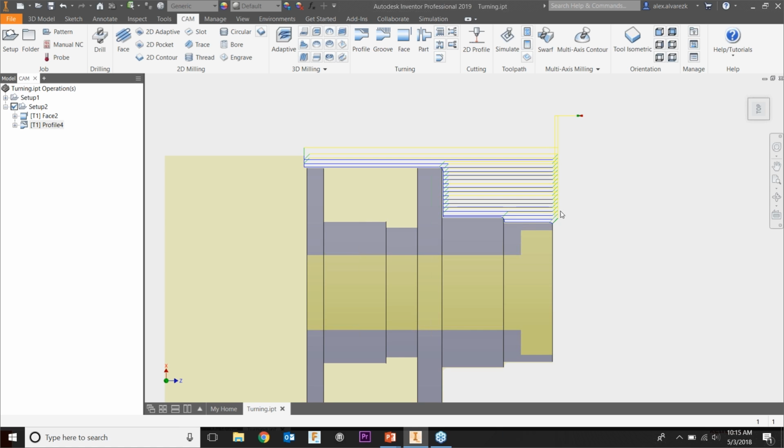Right away, we see that that's a much better looking toolpath. It's not grooving into the part, giving us some weird surfaces here for the grooving tool to come into. And it's not looking at the front of the model anymore as well. So that was a much better toolpath. Now what we can do is make our finishing pass. Again, we can go to the top, select profile, but if we already have some of these parameters selected, we can just duplicate that toolpath.